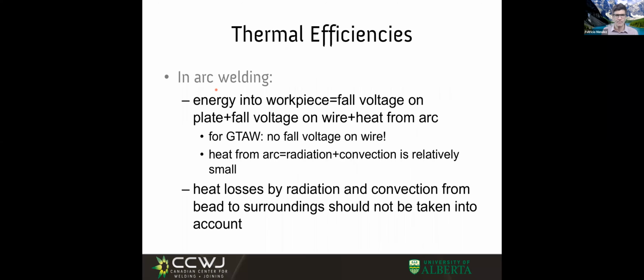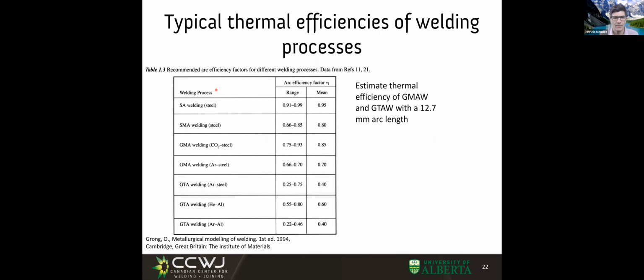And we saw that there are tabulated values, more or less like these ones we have here in this book. I also suggested, based on the energy rates we discussed when we talked about voltage and power in arc welding and the deposition in arc welding, that we can ballpark an efficiency in a way that accounts for things like the role of electrode extension.